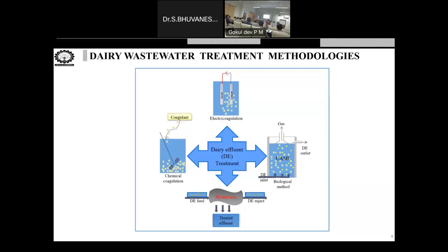What should be the factor now? The emulsion should be very stable in nature. It should be stable even for 2 months, 3 months, or at least for a week, 7 days or something, so that at least one process will get over. For stability, emulsion stability plays a very big role. For that we can add some emulsifiers. Like that, carriers we can add. This emulsifier will make the emulsion stable for a long time, so the liquid membrane will be stable for a long time.